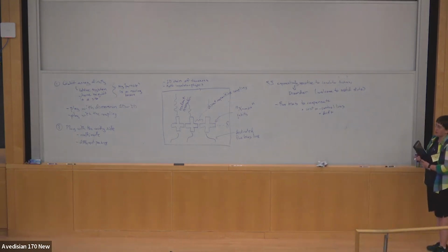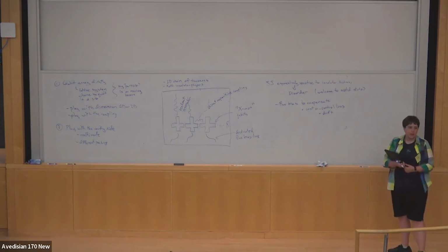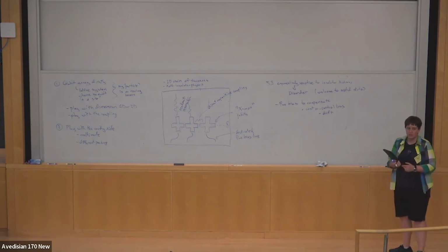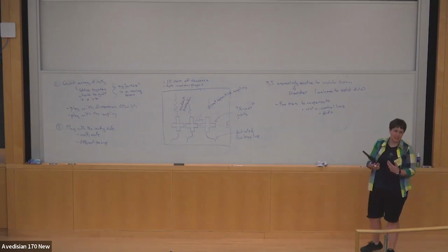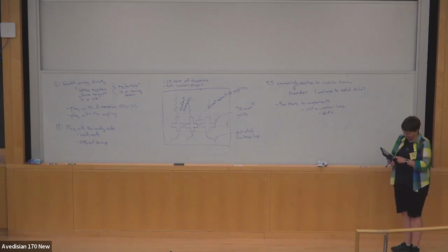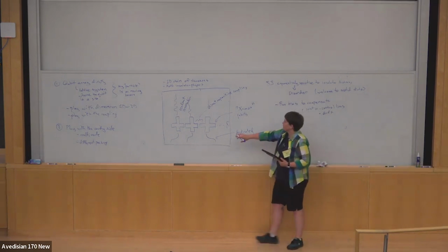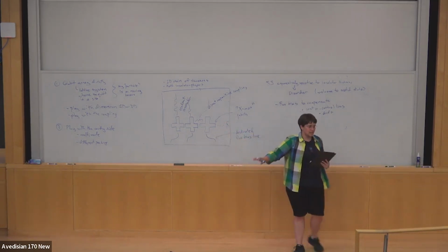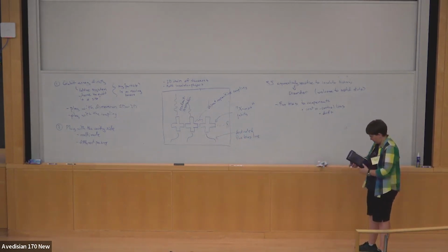And so when you're designing a superconducting qubit architecture, you're sort of always trying to trade off these two issues. Can I live with the different Josephson junctions, or do I need to tune them exactly the same? What's the minimum number of tuning knobs that I can get away with? You know, how many $1,000 of power supplies and how many servos do I actually want to have? And so that's what all these flux bias lines are for. And so for an 8-qubit device, there are 8 individual flux bias lines. So it's 8 DC voltages going into this device to control the qubits and make them degenerate.